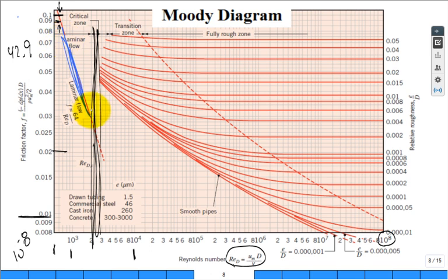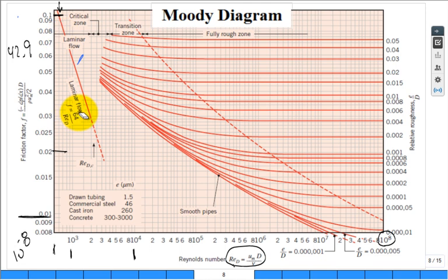It's in the laminar flow region, and we have the friction factor given by a simple expression of 64 over the Reynolds number. On a log-log plot, it's a straight line. Otherwise, it's not a straight line on a linear plot. Do they have multiple curves over here in laminar, or just one curve, and it's 64 over Reynolds number? Just one curve. All right, let's take a look.